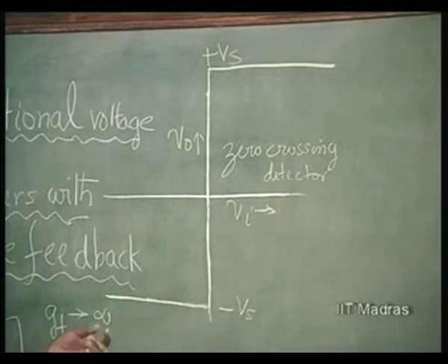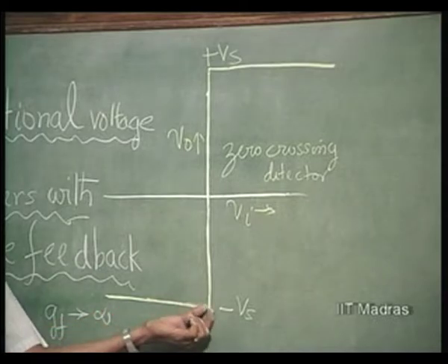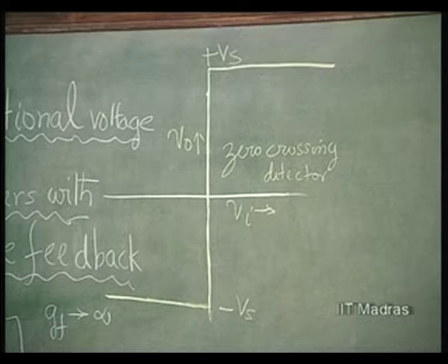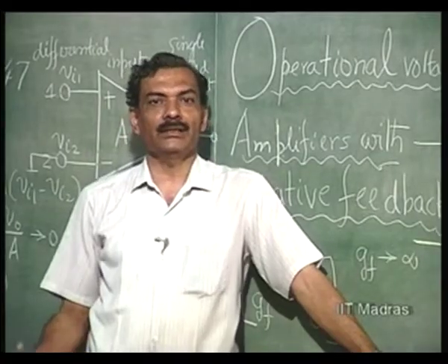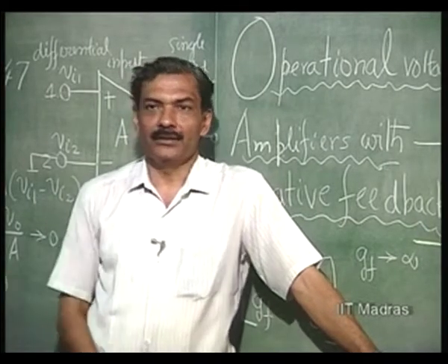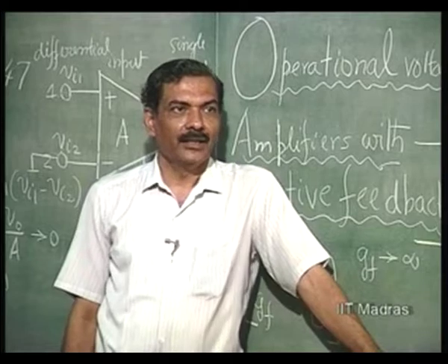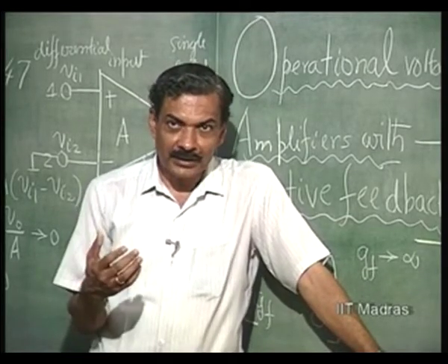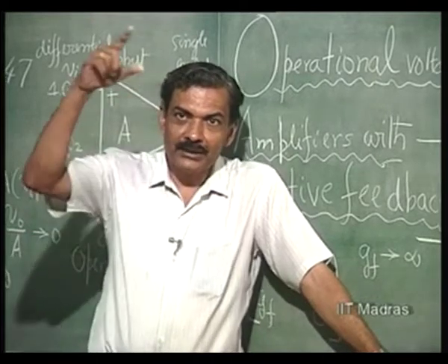So, it tells us to a great degree of accuracy when exactly the input voltage crosses 0. Where do we use this zero crossing detector? Normally, when we design electronic switches, these switches operate, let us say, on a power line. When the power line is being switched, we would like to switch exactly when the voltage is crossing 0.